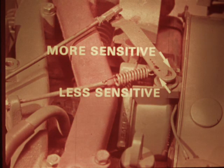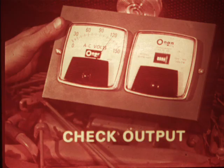To make the adjustment, move the spring toward the pivot shaft for more sensitivity to reduce roll, or away from the shaft for less sensitivity. After a sensitivity adjustment, it's also important to recheck the no-load and full-load output settings again. Be sure to also check the governor-to-throttle linkage rod adjustment if the governor does not respond to load changes.